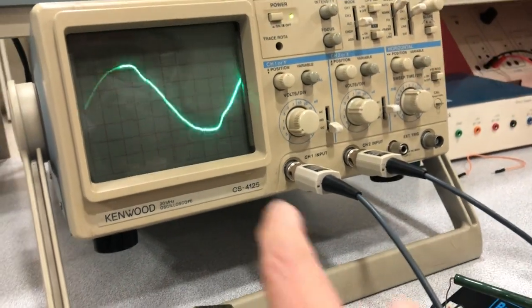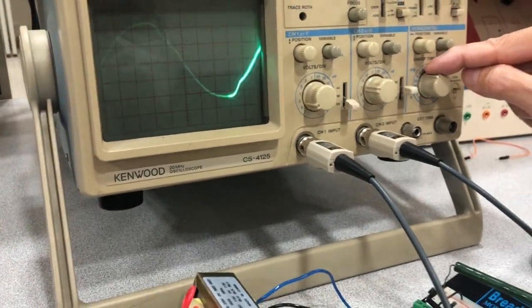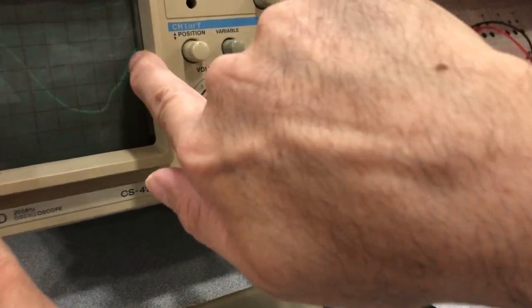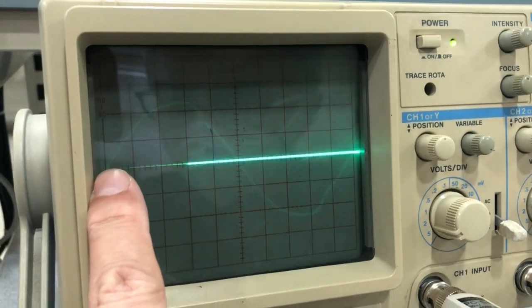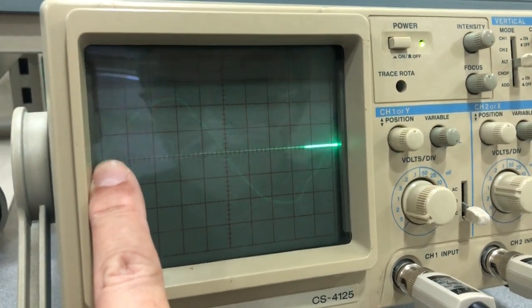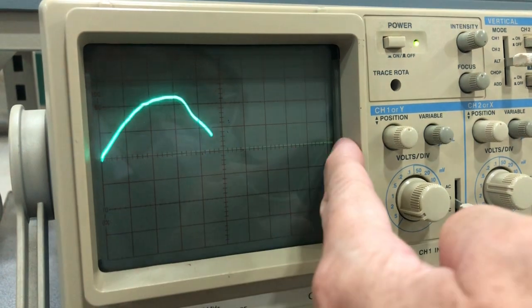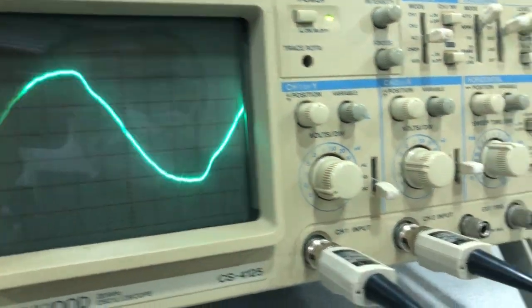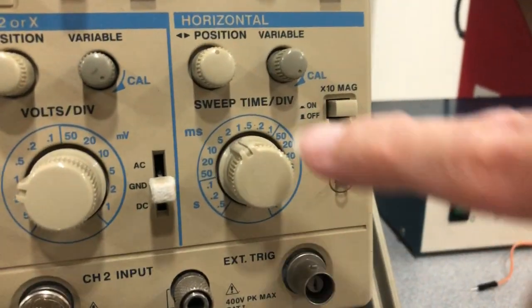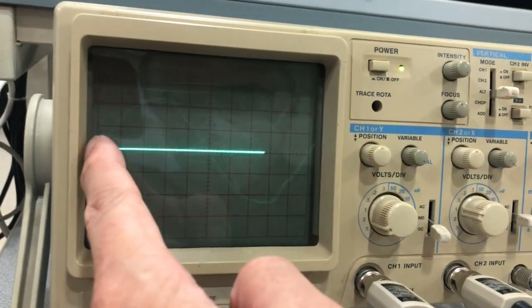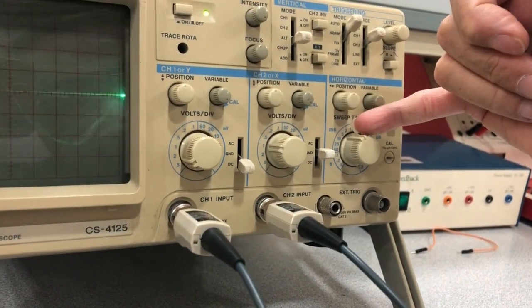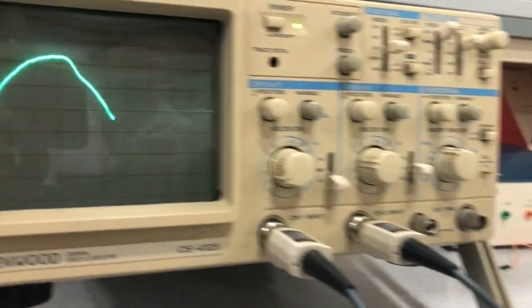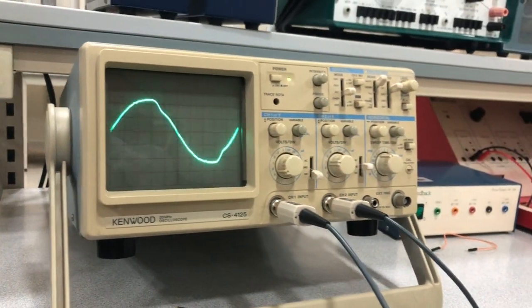Remember, this is 50 hertz. So it is set at 2 millisecond, and from 0 to 0, I have 10 times 2 millisecond. That's 20 milliseconds, which is the inverse of 50 hertz. 20 millisecond, 2 per division, and I have a total of 10 divisions from 0 to 0. So I'm plotting one cycle only. I have 2 millisecond per division, and this is how you make your frequency measurement. You count the period squares, and you know each horizontal major division is 2 millisecond, times 10 is 20 millisecond. You take the inverse, you know the frequency is 50 hertz.